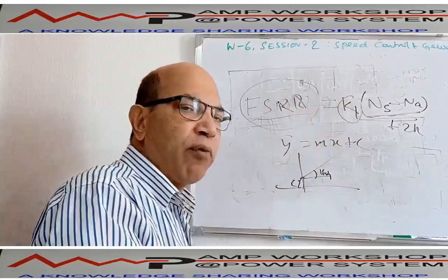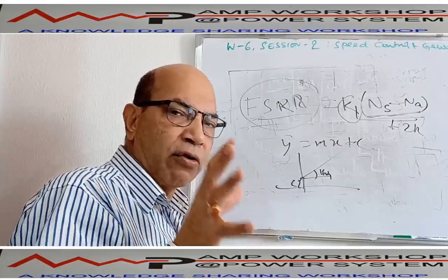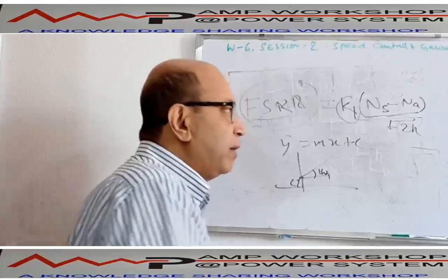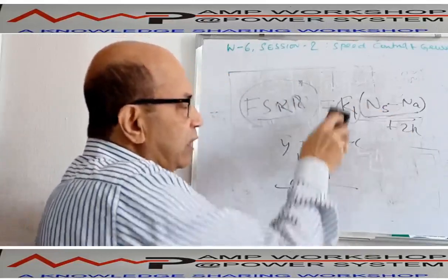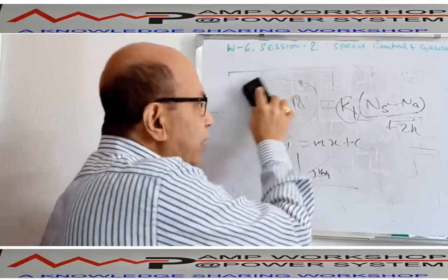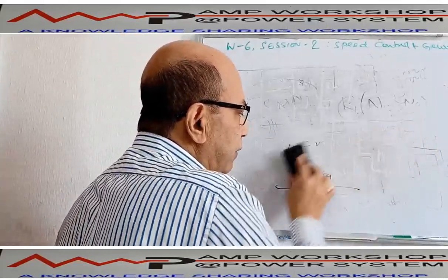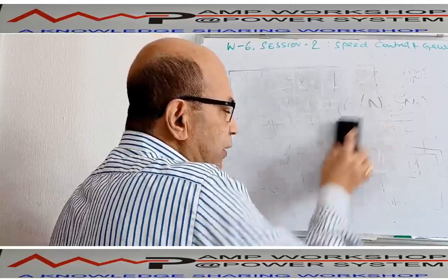So this equation follows the final control element of the turbine. How much fuel will go will be decided by this difference. So this equation is maintained in the governor to calculate this control signal. Okay, this is one of the small points I discussed.